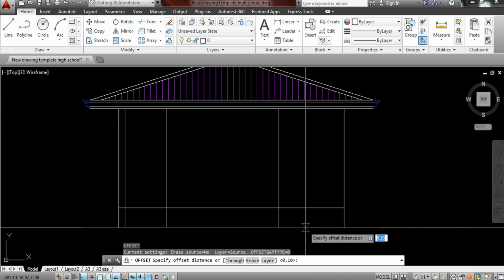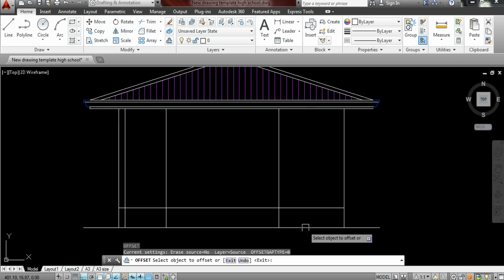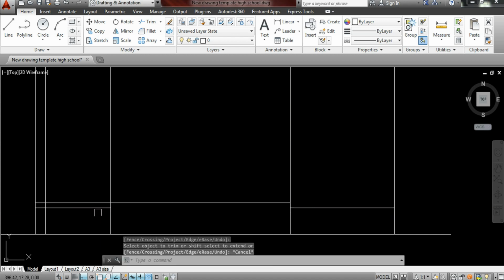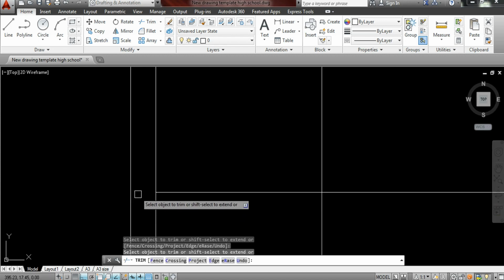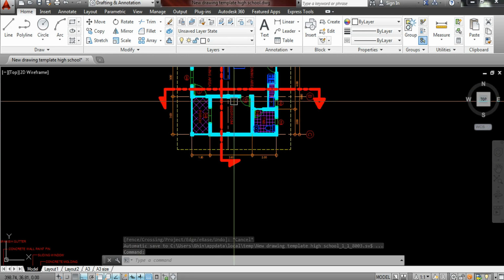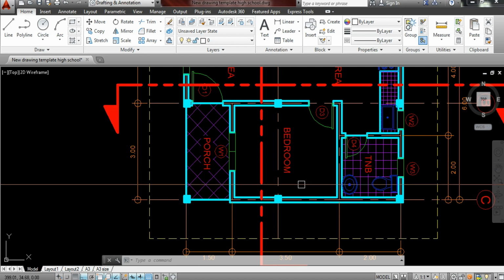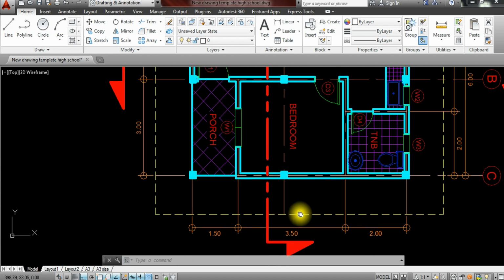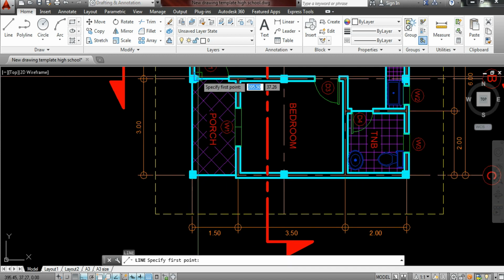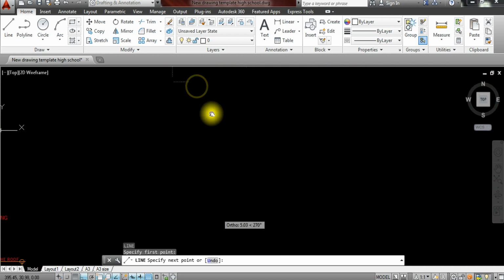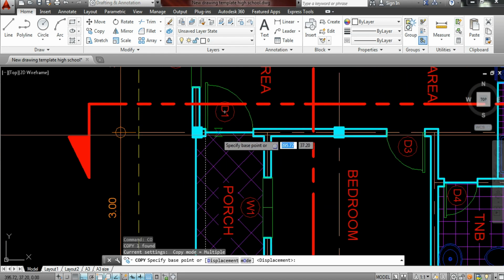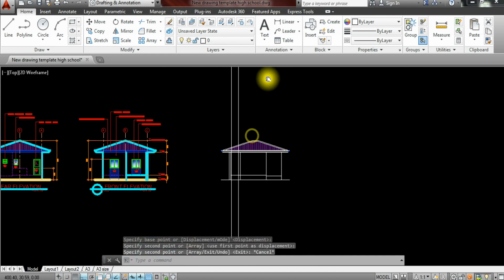Okay, so remember, I'm going to adjust here the size of the toilet and bathroom flooring kasi remember, our toilet and bathroom is lower compared sa standard na flooring na meron tayo. Okay, and then what I should do here is to simply project downwards the door. Okay, kasi ang door lang naman ang naka-expose dito sa kabilang side. Okay, kasi walang ibang mga objects nandito kundi plain wall lang. So I'm going to project line here, going downwards, baba, and then copy this one to the opposite side para malaman lang natin kung saan ang position ng pintuan.